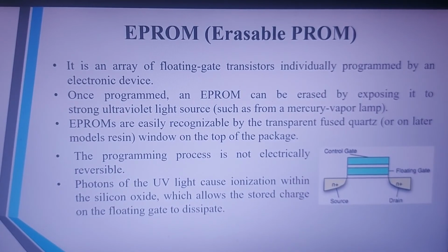As I said, EPROMs can be easily recognized by the transparent fused quartz, or later-model resins. In the later versions, resin is used. Transparent fused quartz was used originally. As I said, on the top of that IC package there will be a window, through which UV rays have to be passed.